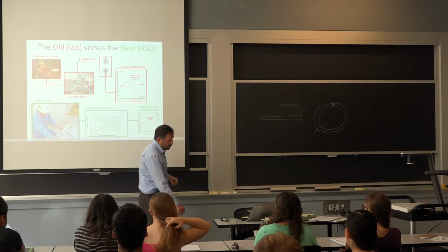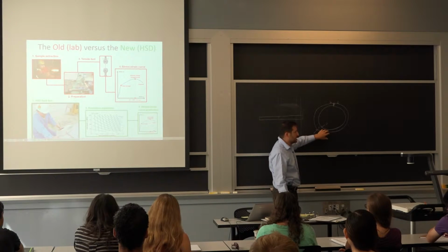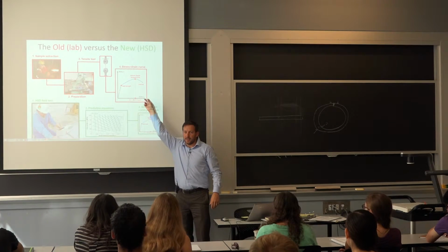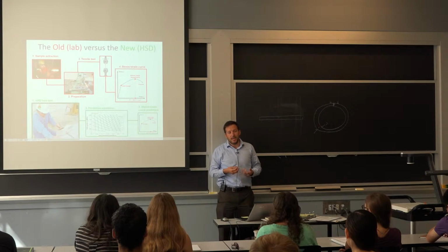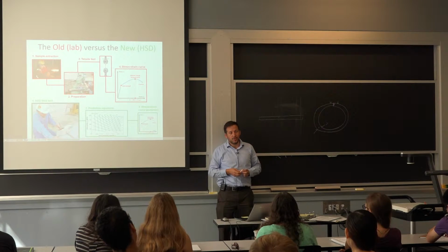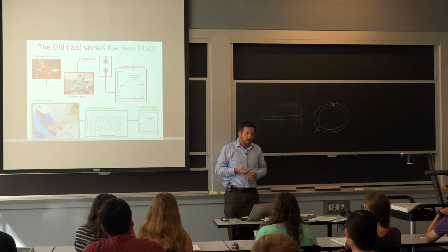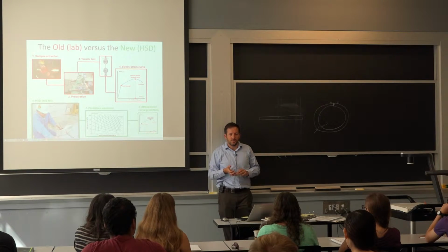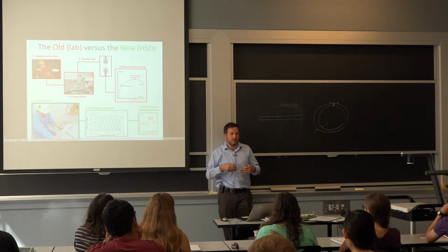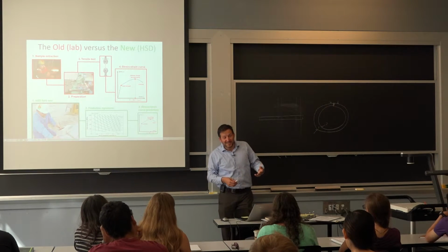Now, why is this all important? The rule of thumb, the industry standard, still is this tensile test that tells them what is the grade of the pipe, what is the minimum pressure that I can put in this pipe. So ultimately, through our analysis, we want to back determine that, mainly because not only is it old construction, but they did not have good testing records of what was put into the line. So they'll know, okay, we've put this type of pipe, this diameter, maybe this thickness, and that's it.